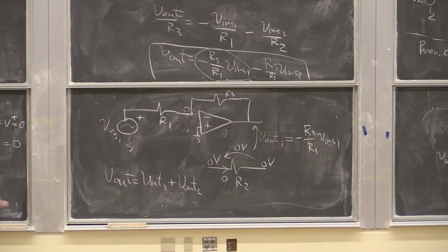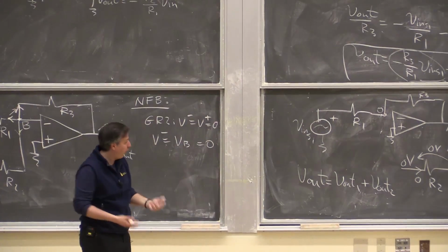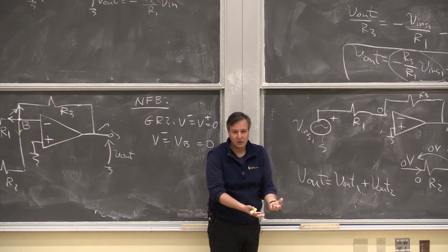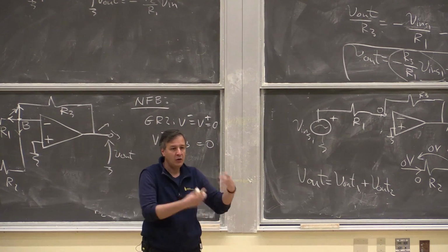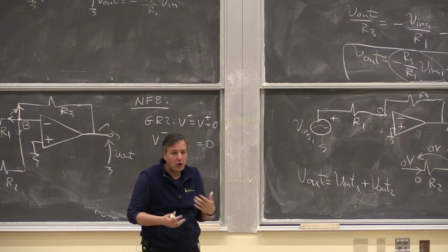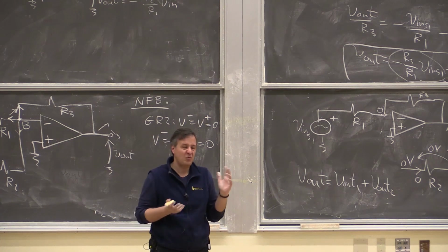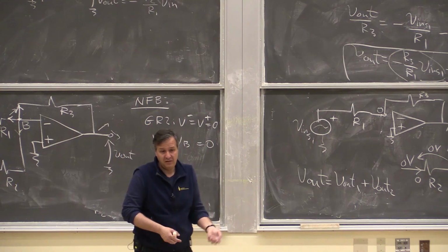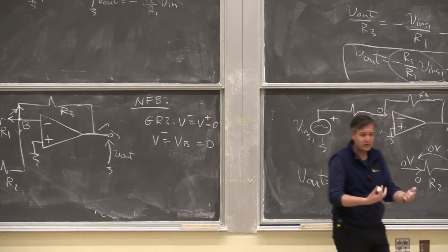Now, this all depends. So what is easier? Is the nodal easier for you? Nodal was not that complicated in this case, right? But hopefully in time, you'll be able to do this quickly. Just null the source, simplify again the topology, see that this topology is something you recognize immediately what it is, and just write the formula, right? Rather than going to nodal. Op-amp circuits are not going to become very complex nodal circuits. You will at most have like 2 nodes to solve, but pretty much 1 node most of the time. So you can go down that route, it's just gonna take you time, and you're losing insight. This way, you kind of see what the circuit does immediately, right? And that helps you compose circuits more efficiently.